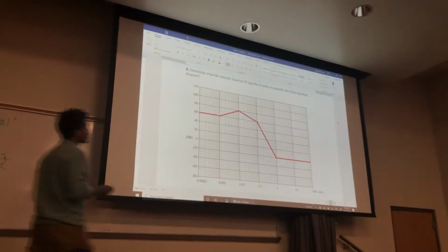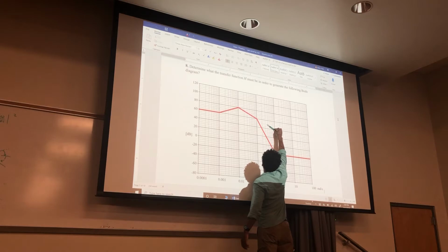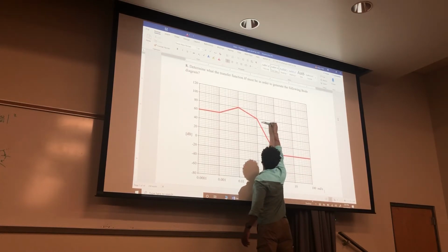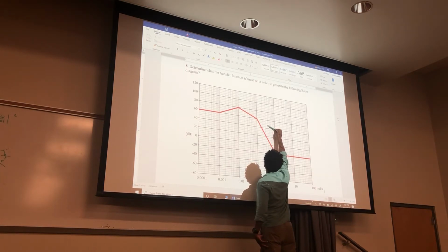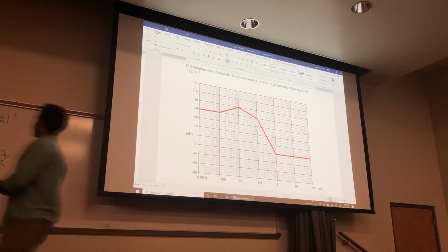Now this one right here would go off like this at -20 decibels per decade. But if we do it again, it's like 1, 2, 3. It's like 3 orders more.